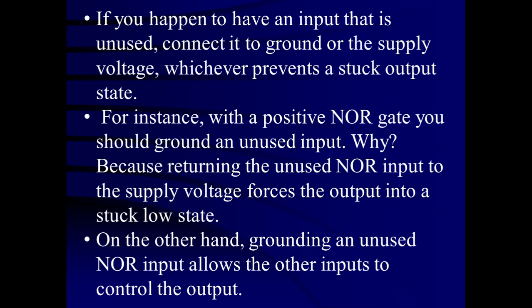If you have a 10 input NOR gate, and any one of the inputs is connected to 1, the output of this NOR gate is definitely going to be low. Any one input of the NOR gate will force its output to be low, irrespective of the other 9 inputs, whatever they may be.